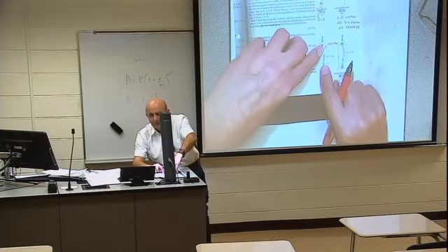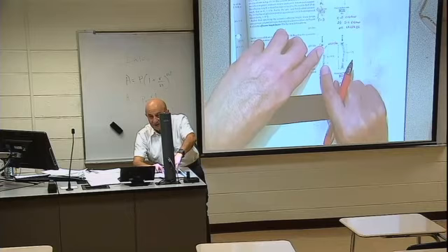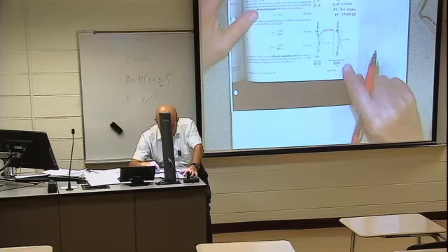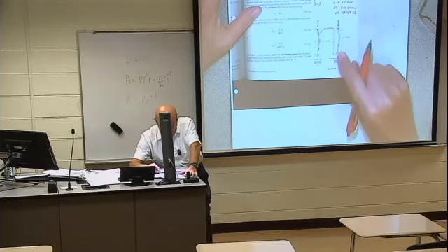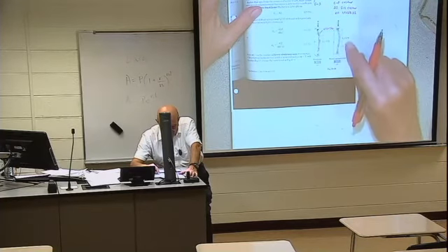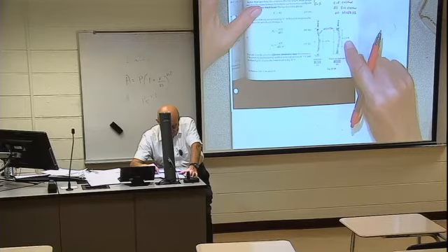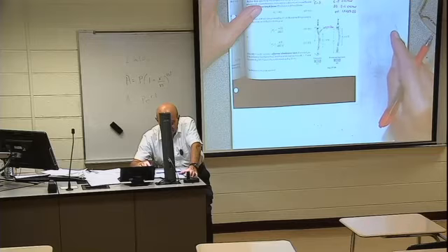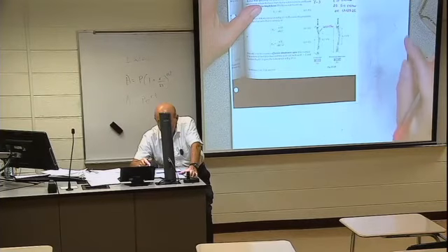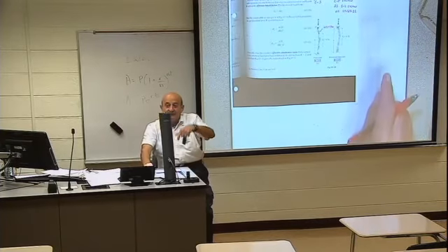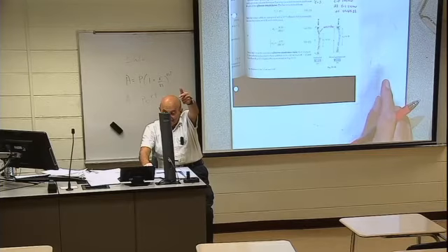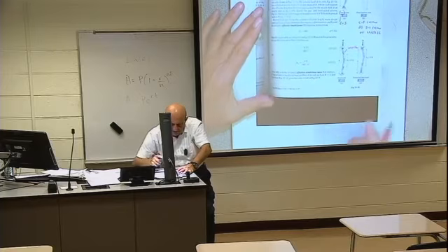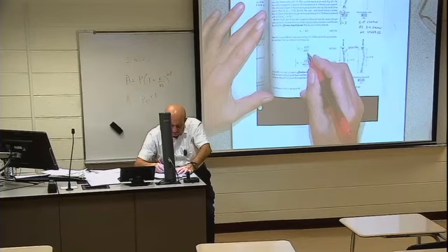Therefore, buckling load will be 4 times bigger. And for the simply supported and clamped, the effective length is approximately 0.7, because below we have 0.7 times 0.7 will be 0.5. So 0.5 below gives me 2 up. Okay? So that is this P critical.